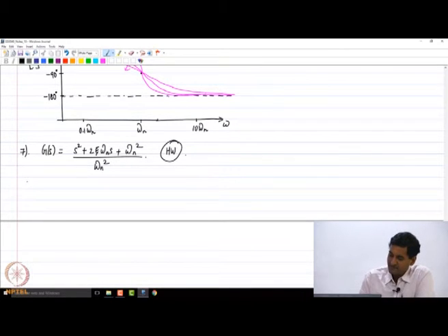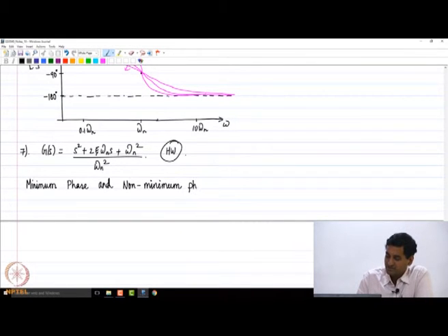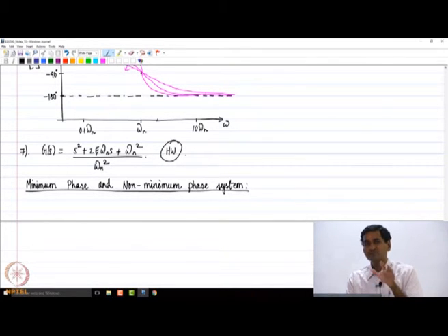Okay, so this next discussion is on minimum phase and non-minimum phase systems. So I told you that when we come to frequency response, I will revisit minimum phase and non-minimum phase systems, right? So do you remember what is a non-minimum phase system? Of course, we are assuming stable systems. When did we use the adjective non-minimum phase? Do you remember? When there was a zero in the right half plane, right? That was a non-minimum phase, right? When all the zeros are in the left half plane, it's a minimum phase, right?